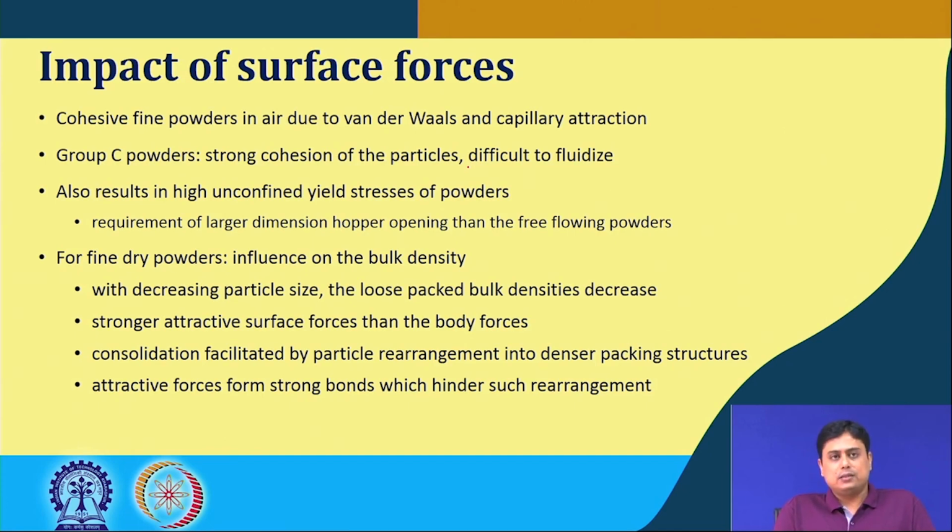It also influences the bulk density of fine powders, because the bulk density depends on the particle size. As the particle size decreases, the loosely packed bulk density also decreases, which may sound counterintuitive, because on reducing the particle size one would expect more and more compact densities. But the point is that consolidation is facilitated by particle rearrangement into a denser packing structure.